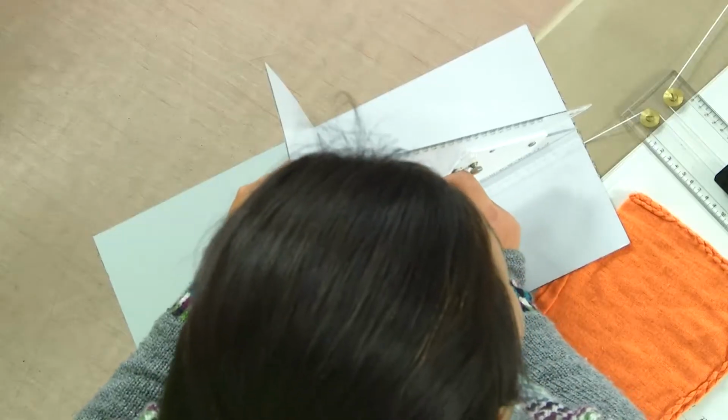Now, if I have a line which is inclined to both HP as well as VP, whatever that line is, if it makes an angle with HP and VP both, the sum total of the angles that it makes with HP and VP will remain 90 degrees. Now, how do we draw that? How do we draw this kind of projection? We could start by doing this as well.